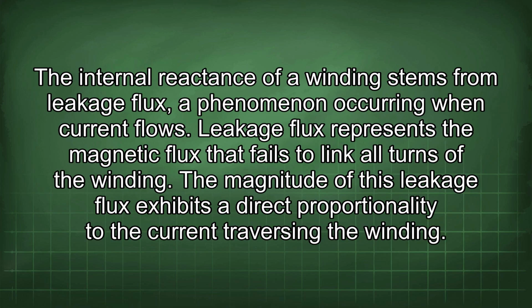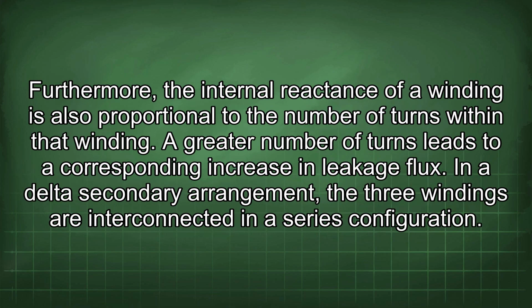The internal reactance of a winding stems from leakage flux, a phenomenon occurring when current flows. Leakage flux represents the magnetic flux that fails to link all turns of the winding. The magnitude of this leakage flux exhibits a direct proportionality to the current traversing the winding. Furthermore, the internal reactance of a winding is also proportional to the number of turns within that winding. A greater number of turns leads to a corresponding increase in leakage flux.